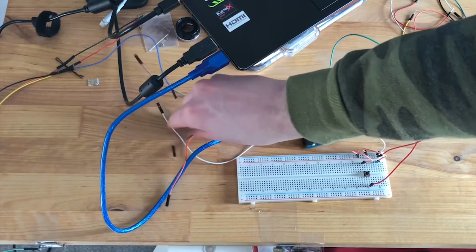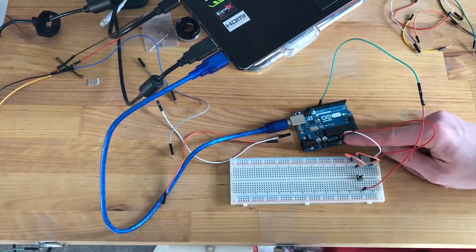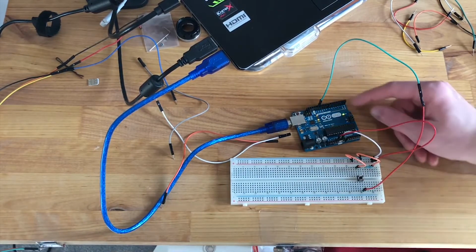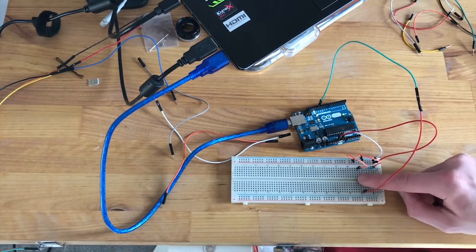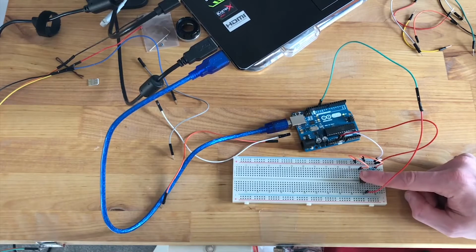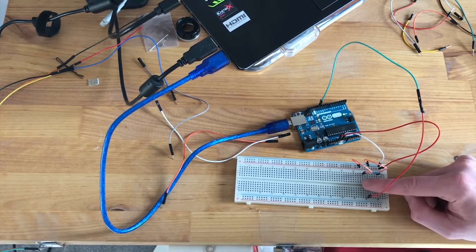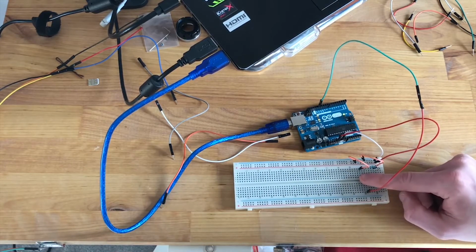So what I have set up at the moment is I've got my Arduino board connected. I've got a ground and a 5-volt power going to one end of it along the horizontal strips, and then I also have a button set up with what I think is a 10 kilo ohm resistor here, and we are going to write a program that triggers it so that when this button is held the laser will fire. When it's not held, it will do nothing.